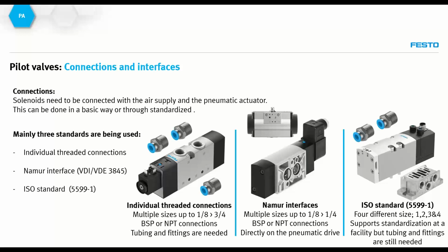The benefit of this is that you have a lot of flexibility in your installation, and also for MRO spare part activities, urgent replacements, this interface allows you to directly place and install a replacing solenoid valve to your installation to increase the troubleshooting at that moment. Still, from the manifold, tubings and fittings are needed. So there still will be fittings, but because they're having a manifold interface, these will not be directly installed on the solenoid valve, but through the manifold.